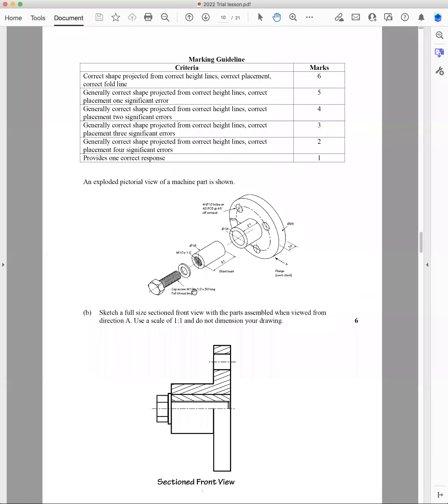In drawing offices, you don't section symmetrical objects fully. You just do a half section. So you've got this steel bush here that is, you can see that it's phi-18 and the hole is phi-18. And so that's a force fit. It's called a force fit. You press that in